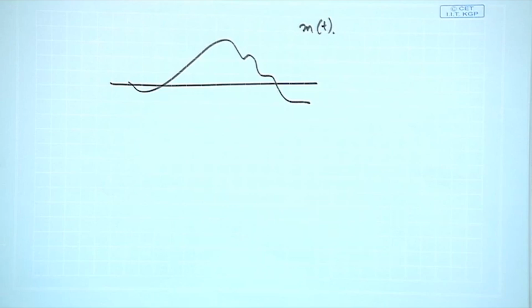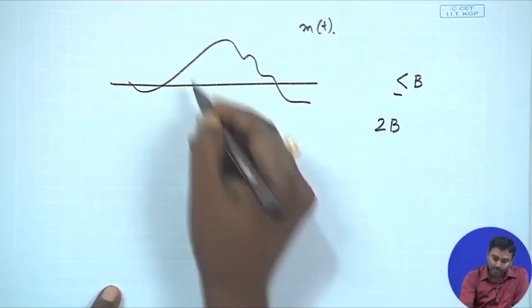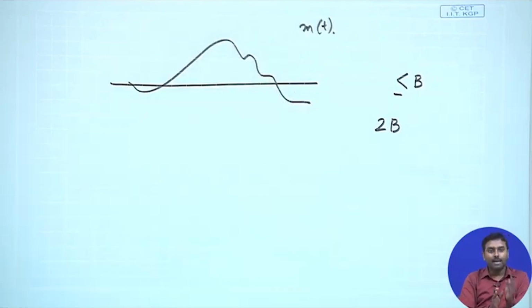First of all, we still have not proven this, but we will resort to the sampling theorem a little bit. Later on we will also prove that, most of you know that this particular signal, as long as it is band limited, that means the bandwidth is less than b, then I have an effective Nyquist sampling rate, which is 2 times of this one. Okay. So, 2b, if I just sample this signal, those samples are already representative of this entire signal.